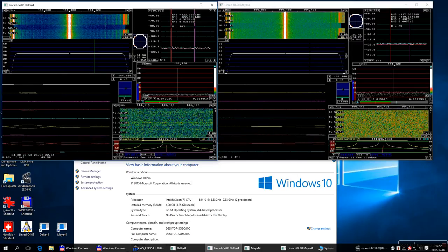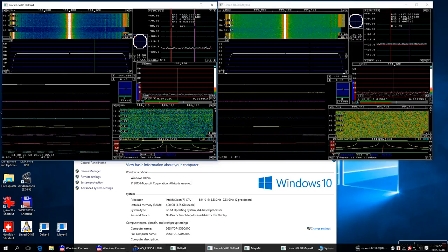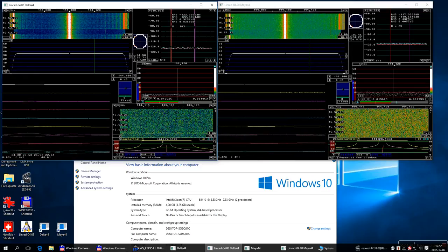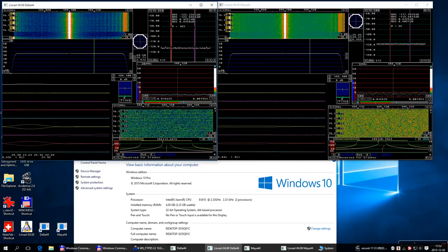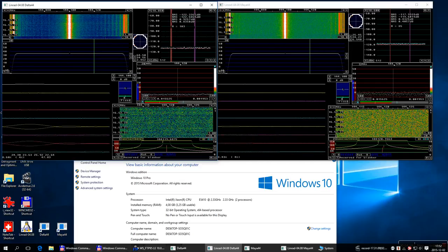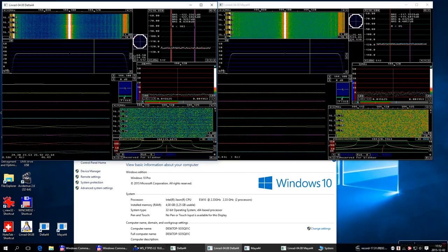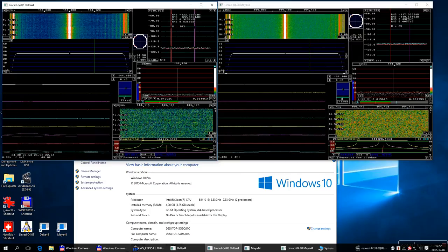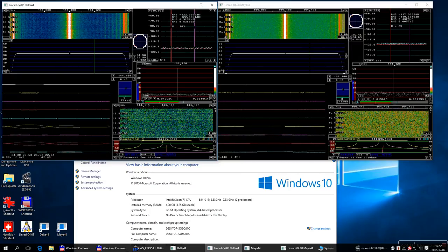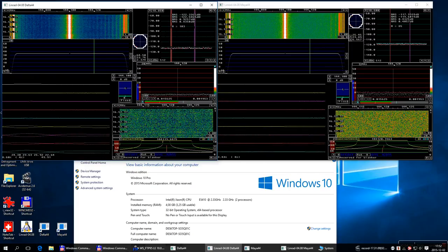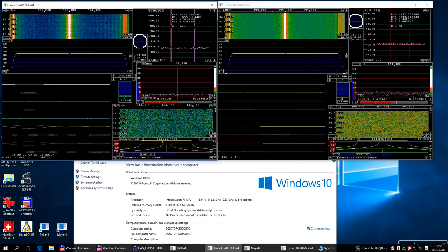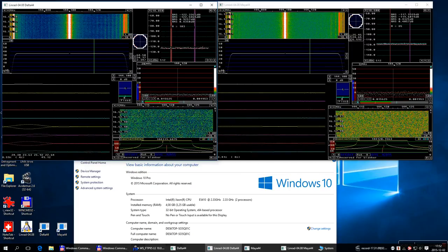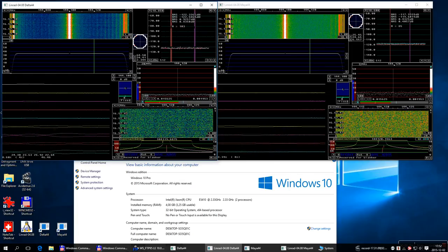So now Linrad is well calibrated, and the interesting thing is I haven't made any addition to the calibration compared to what I showed in the previous video. It's only the calibration procedures A and B. The other two are not used. They will degrade the blanker performance significantly.